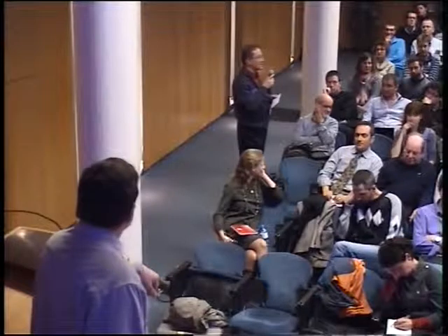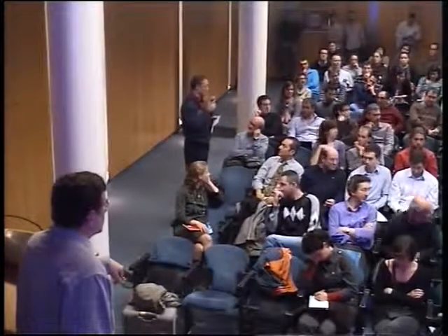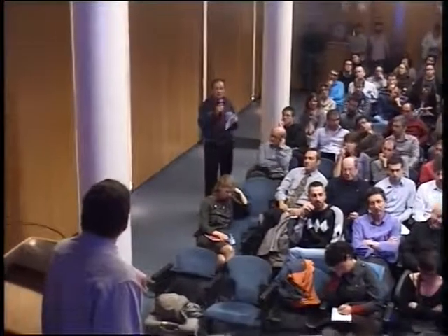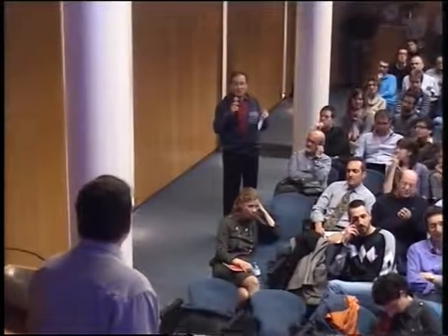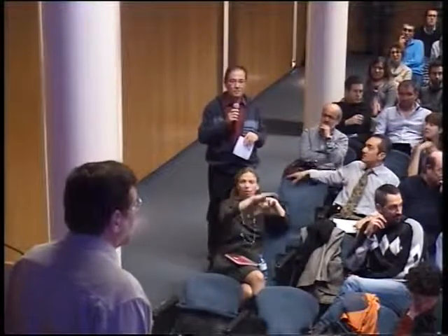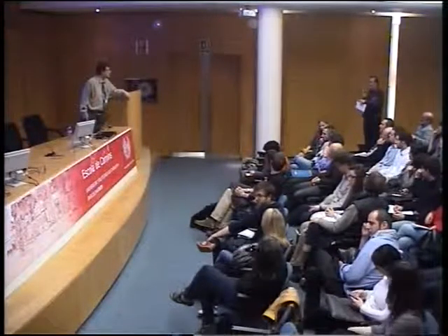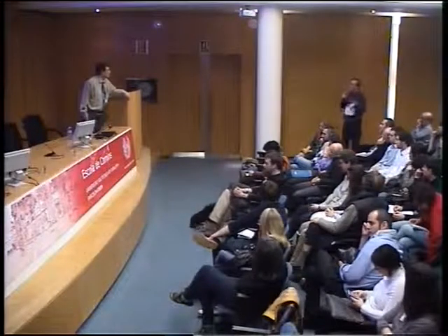Could someone help? Balsa de laminació, we'd say retention tank. Retention tank in urban environments, but basin, retention basin. He's asking about urban rivers where the channel is encroached by the city. And in this country, we are very used to building some retention basins for lamination, to reduce the peak flow. And he's also concerned about the sediment in this case. If the sediment will still pass through the river, or if some effects can come in the river.